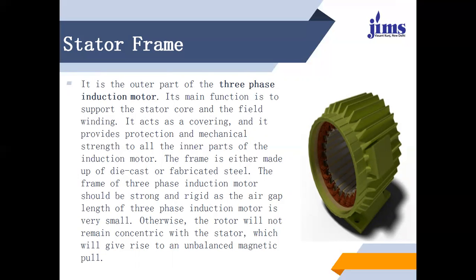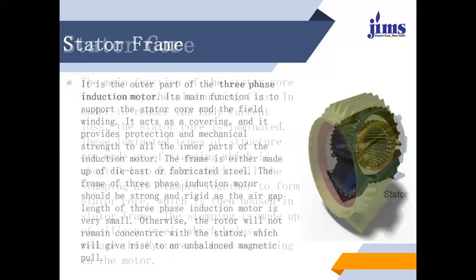The frame of a three-phase induction motor should be strong and rigid as the air gap length of a three-phase induction motor is very small. Otherwise, the rotor will not remain concentric with the stator, which will give rise to an unbalanced magnetic pull within the machine.